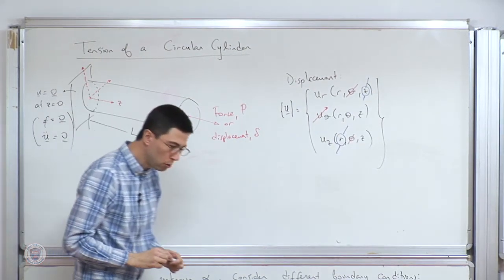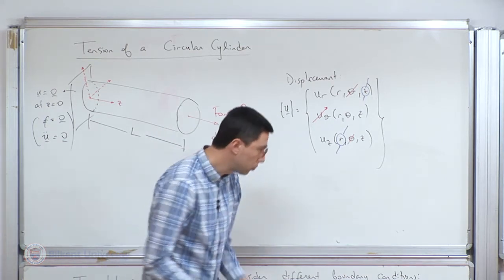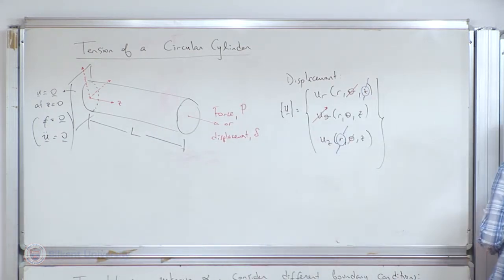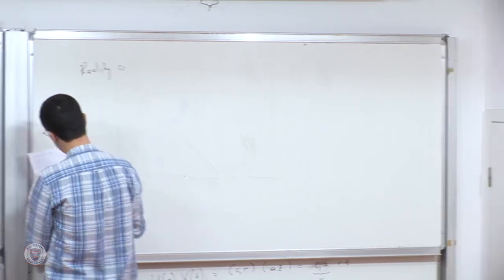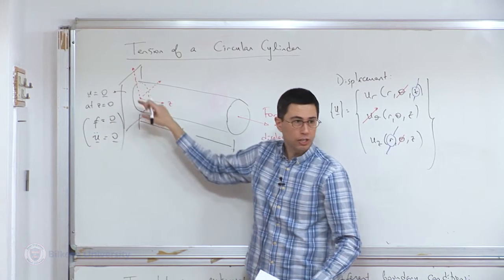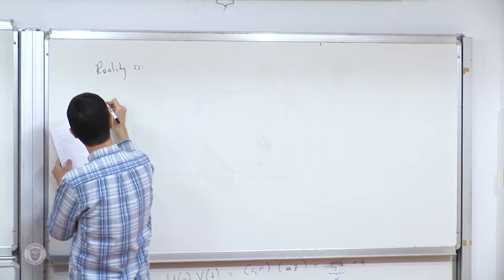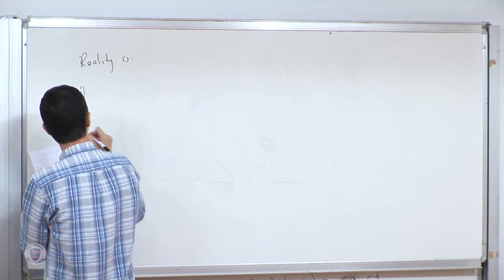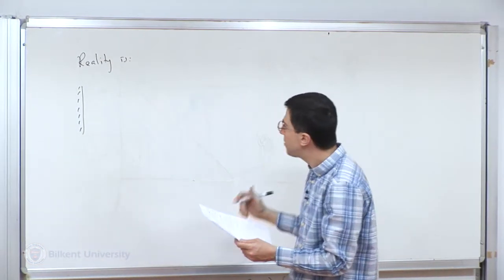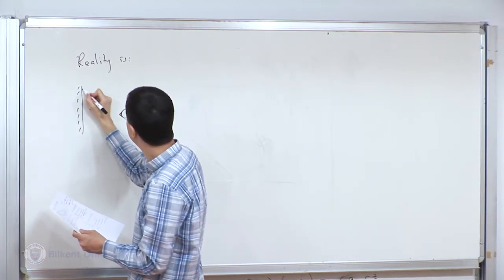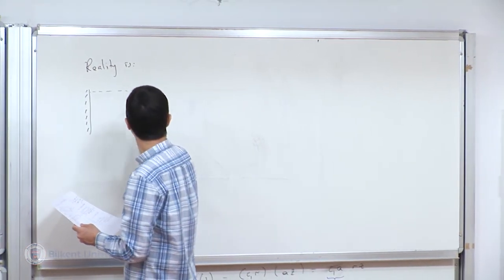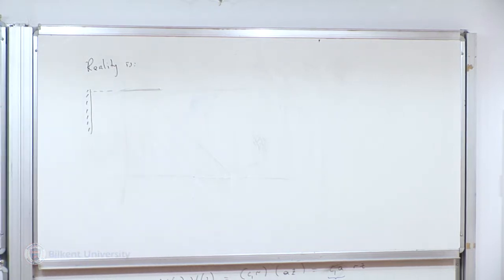Now, the reason I'm crossing out those two terms has to do eventually with the Saint-Venant Principle. The reality is, when we look at the solution of that problem, be careful: I completely constrained all the displacement at the left-hand end. I will show you also a numerical solution of the problem, but you don't really need a solution. You can imagine that since the left end is fixed, and let me make this a little bit neater.